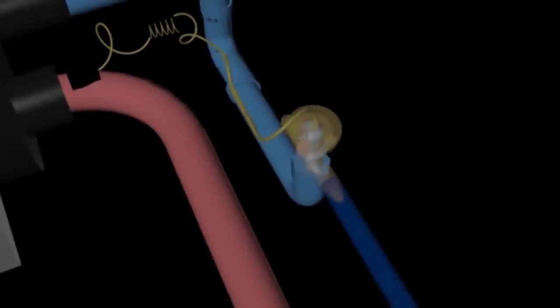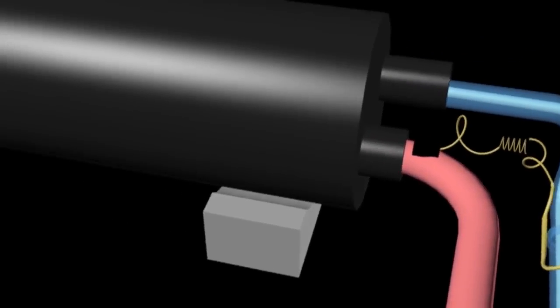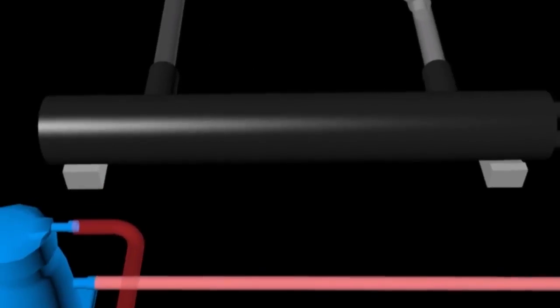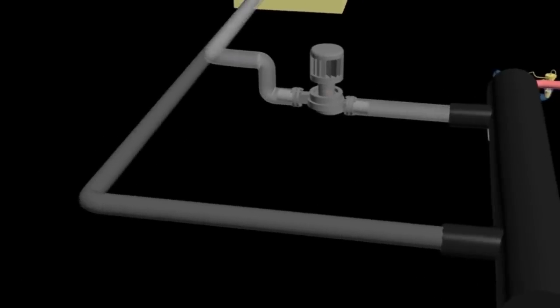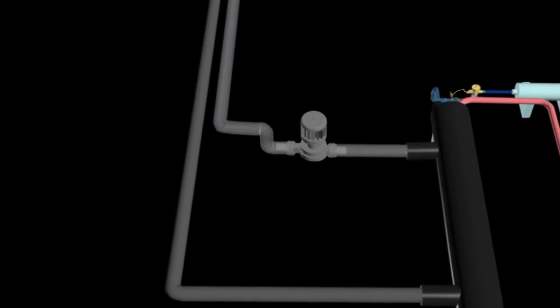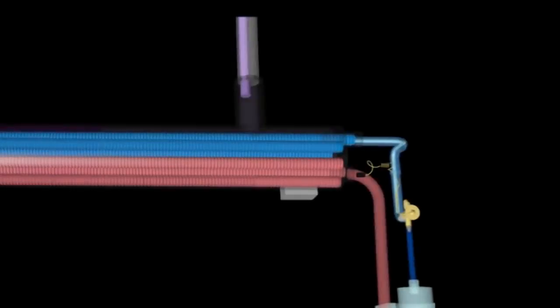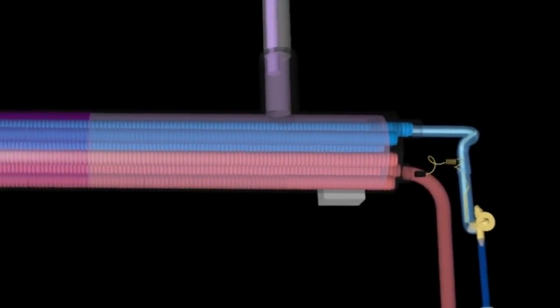Evaporator. The refrigerant in low-pressure liquid form coming out from the expansion valve will flow into the evaporator at low temperature. In the evaporator, the heat from the chilled water which comes out from the air handling unit will be absorbed by the refrigerant due to the temperature difference produced. When the liquid refrigerant with low temperature and pressure absorbs heat from the chilled water, the refrigerant will evaporate to